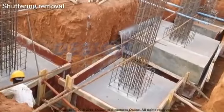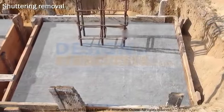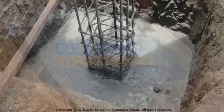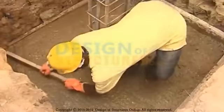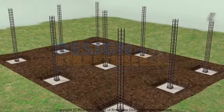Shuttering removal. The formwork removal procedure should be supervised by the engineer to ensure that the quality of hardened concrete and structural member is good. That is, it should be free from, or have minimum, casting defects such as honeycombing, size and shape defects, etc. These defects in concrete influence the strength and stability of the structure, thus immediate repair works can be done or the members can be rejected.